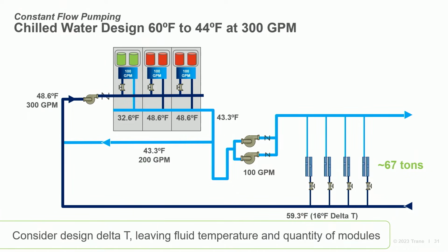This may look okay, but we have to consider that the chiller controls must also protect itself from freezing. To do this, the controls limit the module level leaving water temperature to 36 degrees. So in this example, the module in operation would actually shut itself off to protect the heat exchanger from freezing. After all timers have been satisfied, the next available compressor would be energized. This condition could lead to excessive compressor cycling and varying temperature swings. A variable speed compressor on the first stage could be an option to consider here.